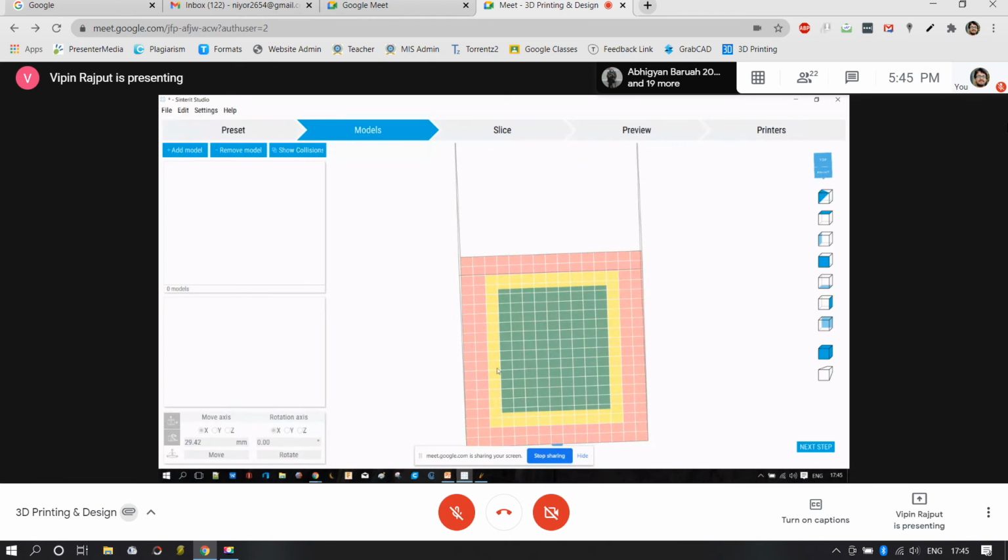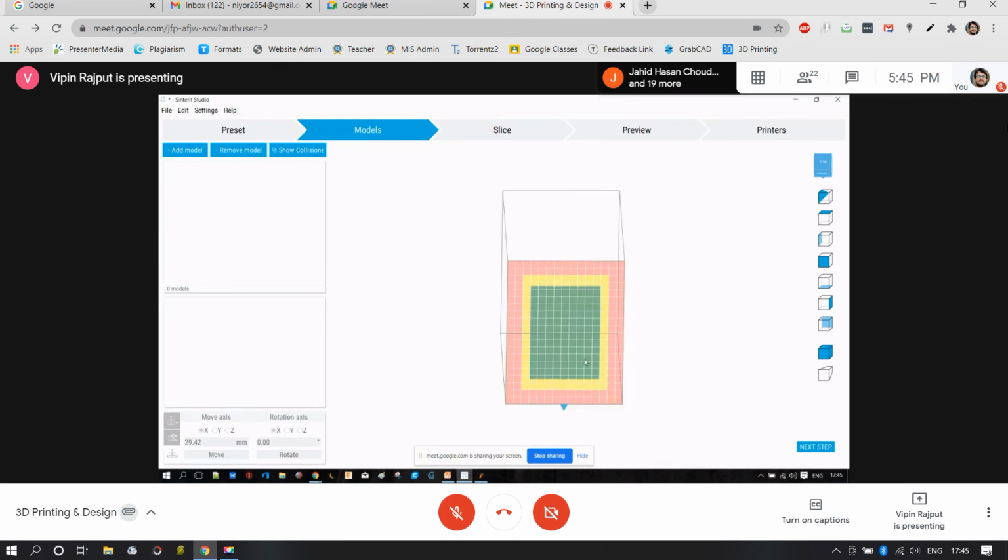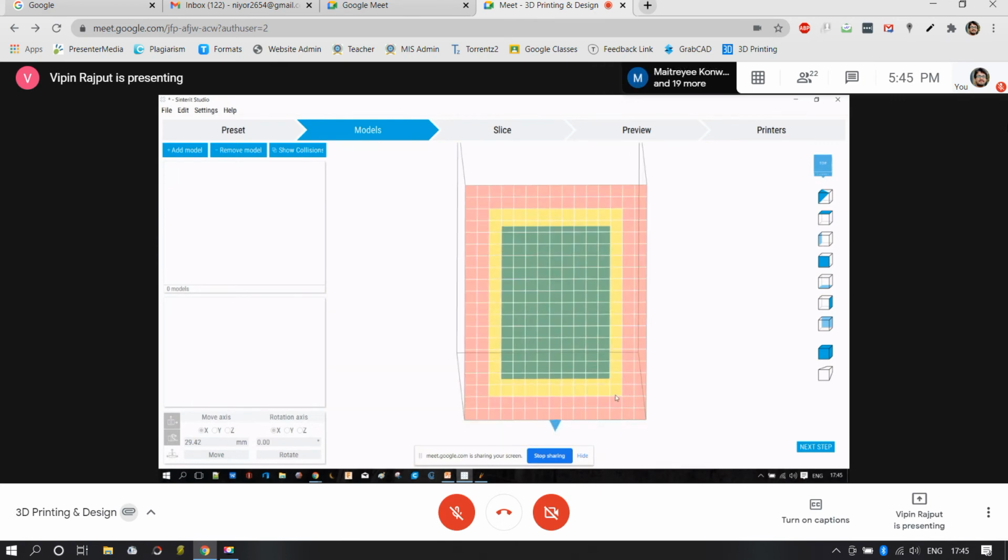Then just beyond this green zone is the yellow zone. If your model lies in this yellow zone, it may or may not experience some sort of distortions or deteriorations. Let's say your model was on a 1 to 1 scale. Within the process of printing, your model can experience either a shrinkage or an expansion of some percentage. Let's say it was formed at around 99.5 percent and 0.5% was a shrinkage, or any critical feature may not tend to form.